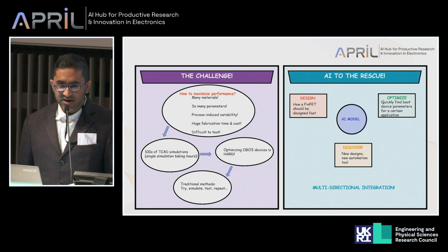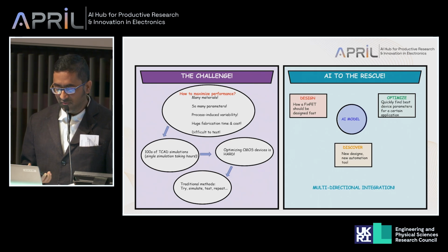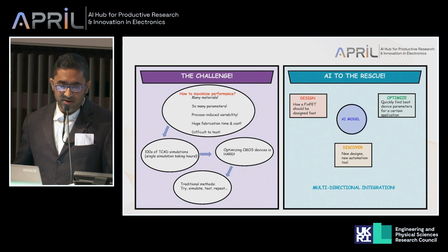One reliable thing is TCAD simulation that people have been doing. Ankit also mentioned, and a couple of other guys, SPAD design, SPAD devices, they have mentioned TCAD simulation. This is a way out. What you can do is TCAD simulation and calibrate with real data. Real data will be challenging to get. Real data means a lot of things: let's say DC analysis, AC analysis, RF data, all data you cannot really get. You can only get a small amount of data. You can calibrate with that data, but that's just the first step, and there are other steps as well.